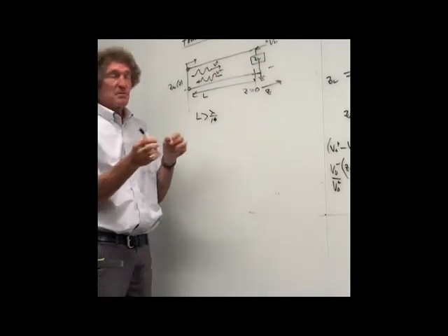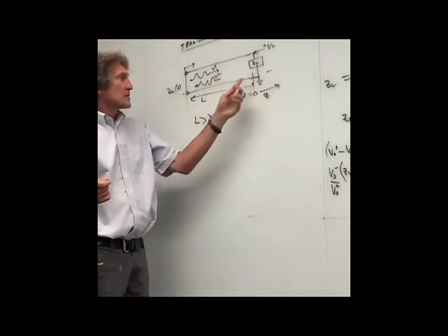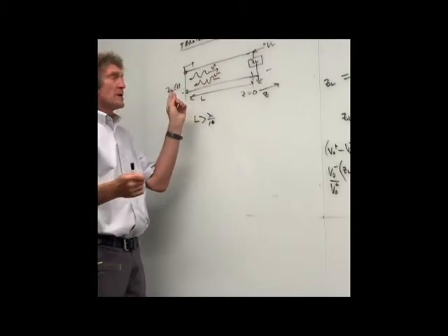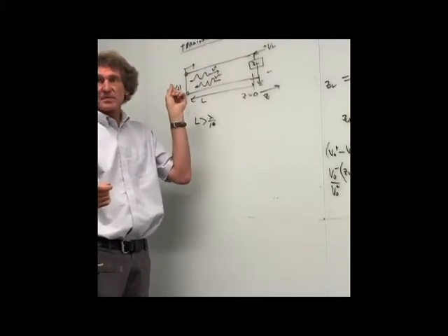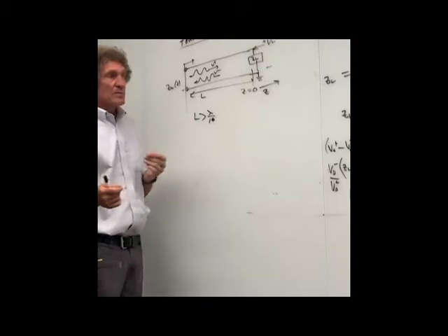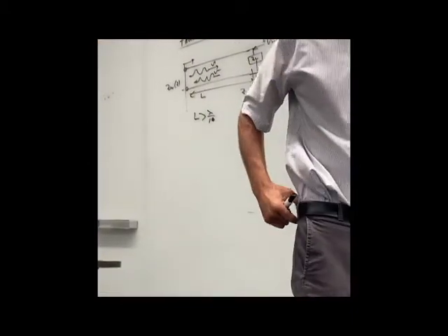You understand? If you just measure across ZL, you get ZL. Well, when these wires are very short, they don't have the ability to form the standing wave patterns necessary for it to behave as a transmission line. But we're going to get the input impedance for that.